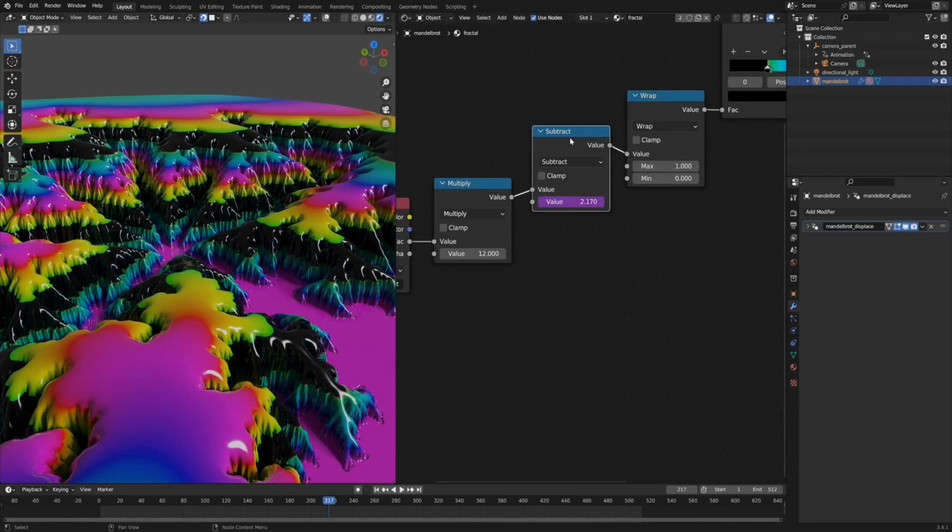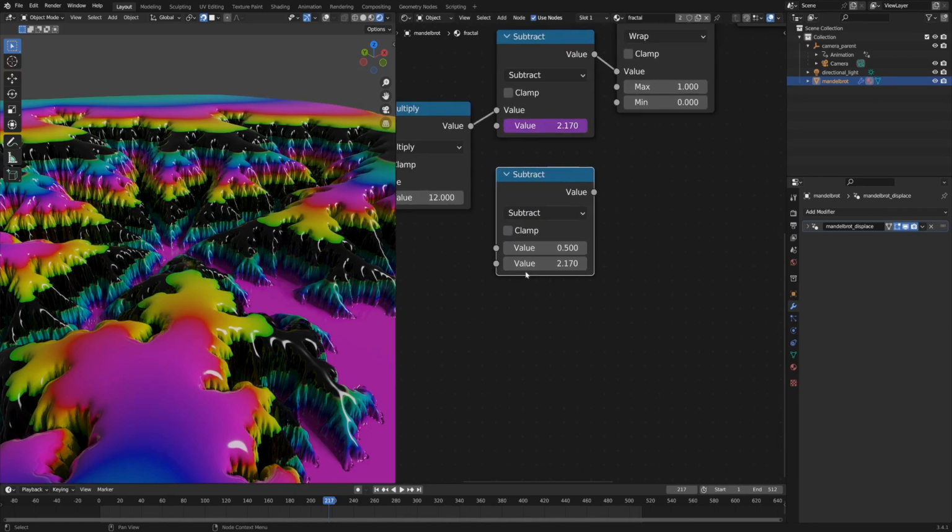And we can look at the expression for the driver by clicking on the value field, and you'll see that the driving expression is the frame of the animation times 0.01. The way you create an expression driver like that in a value field is you click on that field, you enter a hashtag, and then you can use the expression that I have above. That uses an inbuilt expression variable, frame, and then multiply that by whatever you'd like, 0.01 in this case, and you'll get the same value as up here.